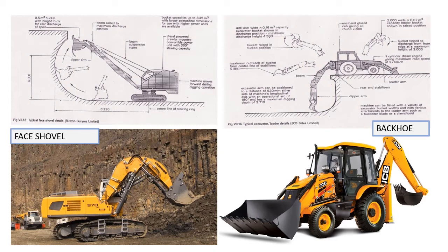We have the backhoe, the most common machine that we have on the site. Backhoe is mostly used where it is expedient to keep the loader at the original ground surface and excavate the ground from the subsurface below this level. Situations of this kind are trenching, canal excavation, and building foundation works.